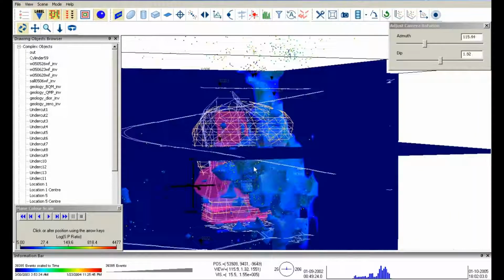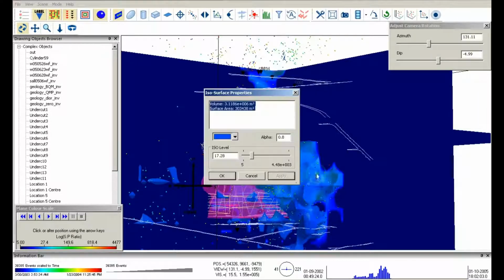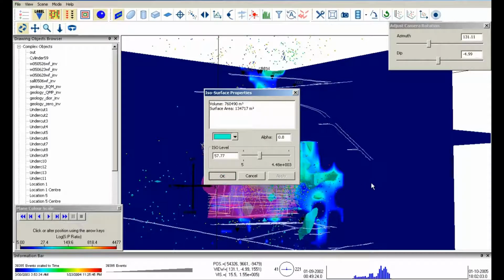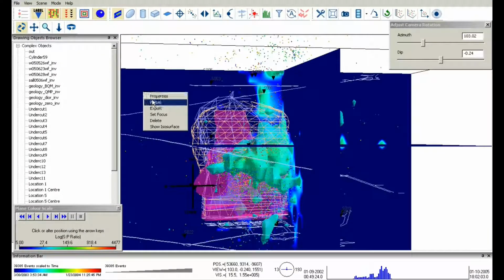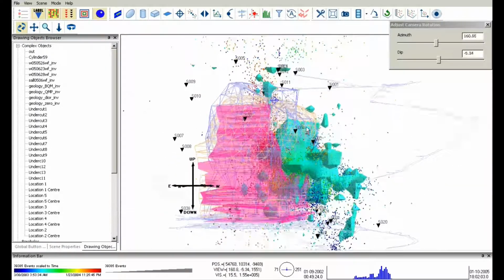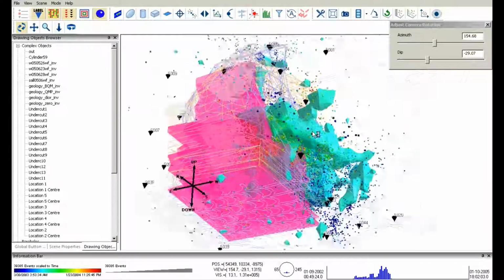By default, the isosurface value is the median. You can see the color corresponding to the value in the same color scale used by the 2D plane, and you can slide the isosurface value and the color changes corresponding to the value you selected. You can select to delete the 2D planes, and that can give you a much cleaner view.